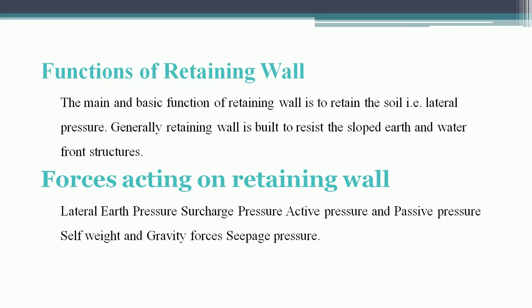The earth pressure acts horizontally, whereas gravity acts downward and reactive forces act upward. Some forces which act on the retaining wall are lateral pressures: surcharge pressure, active pressure and passive pressure, self weight and gravity force, and seepage pressure.